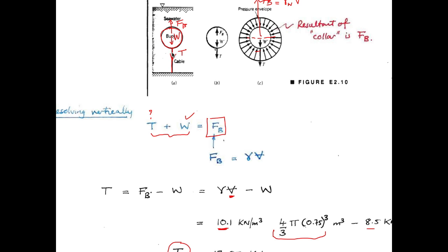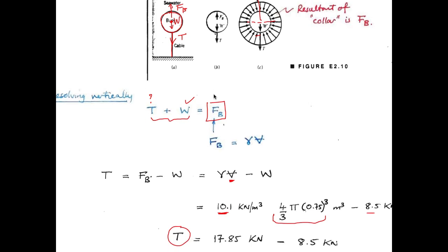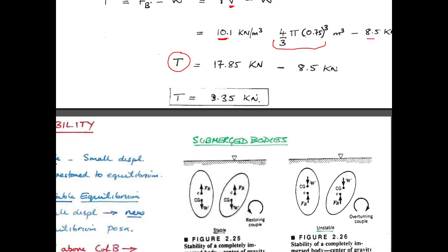We know that the tension acts directly through the center of pressure of this buoy, just from the resolution of all these forces. The weight acts through that location, the buoyant force acts through that location, and therefore the cable also has to be aligned if there's to be no net moment in this. Okay, so it's relatively straightforward.